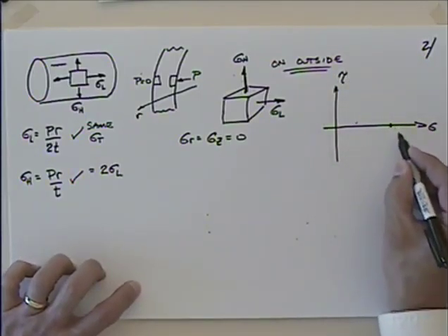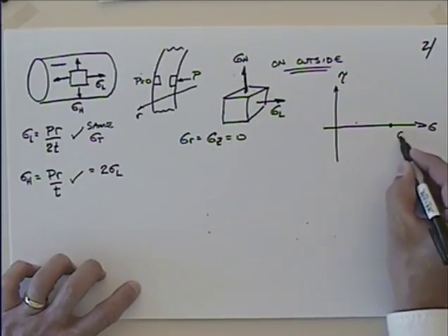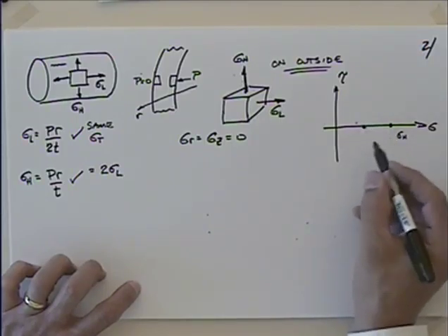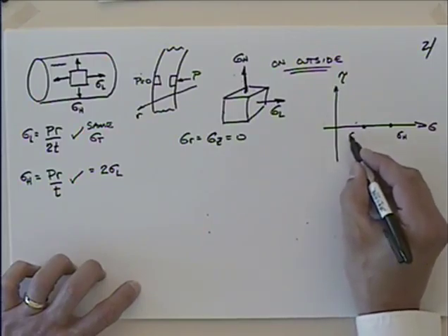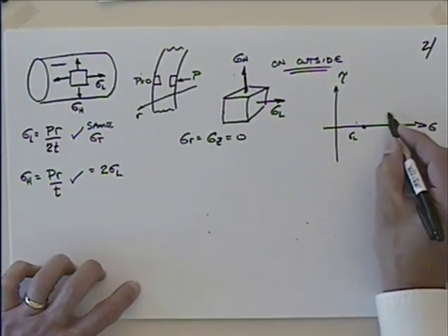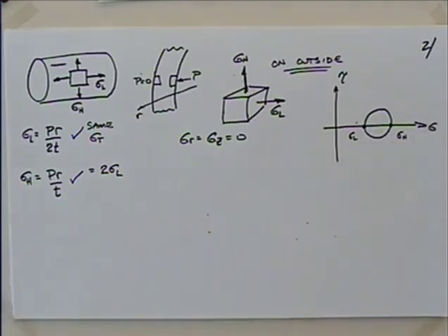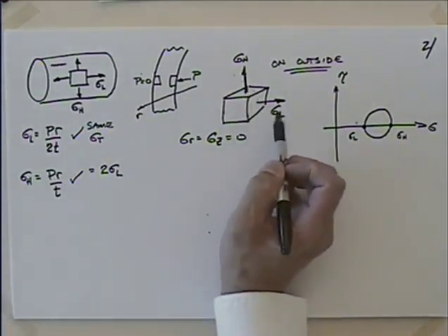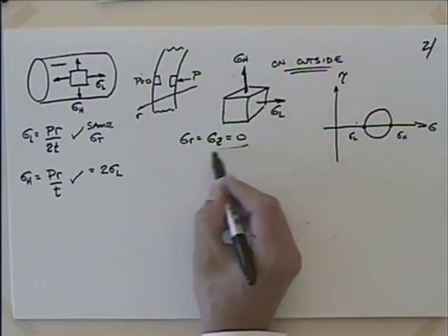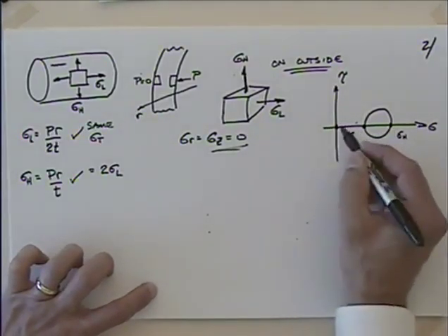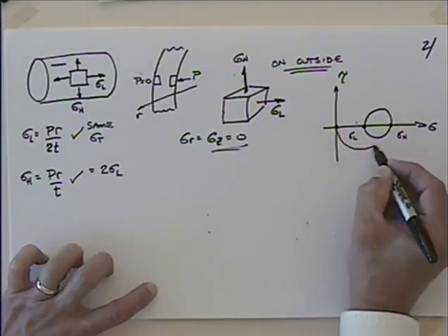So when I put this on Mohr's circle, with sigma and tau, we end up with our hoop stress way out here. There's sigma hoop, and then about half of that is our sigma longitudinal, and we've got a circle right there. That'd be if I just looked in the longitudinal and the hoop direction, but I have sigma z equal to 0, so I can plot that point there, and I get a couple additional circles.